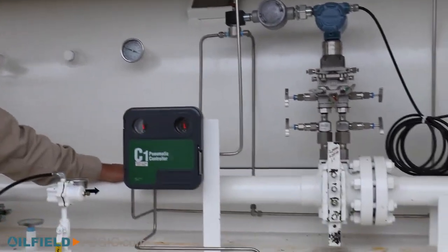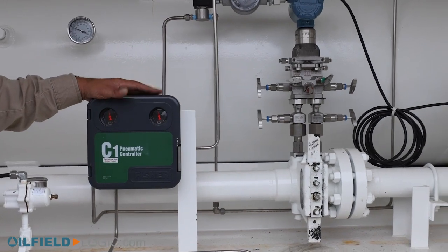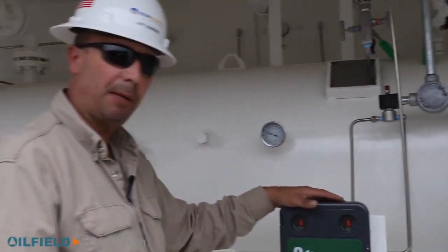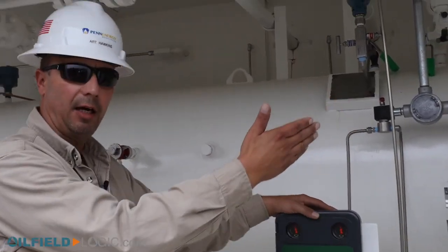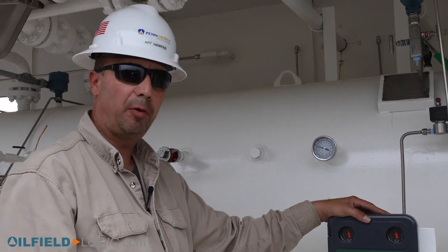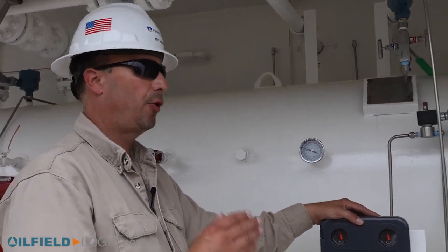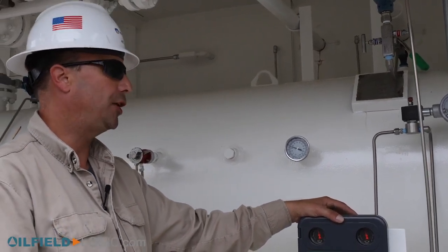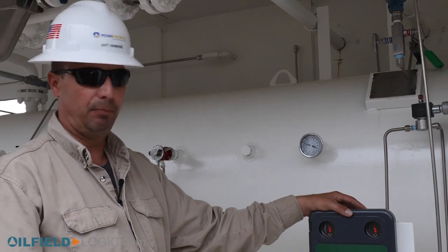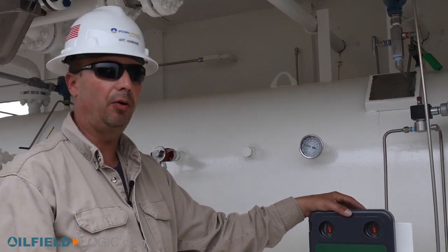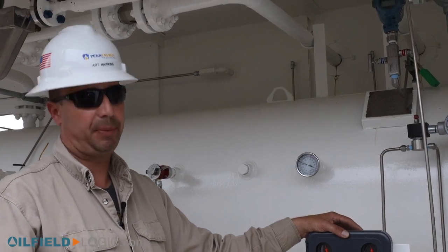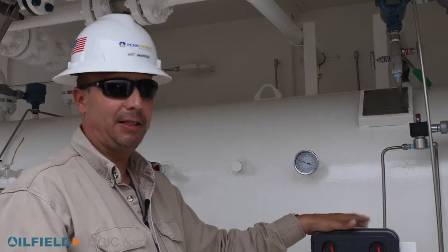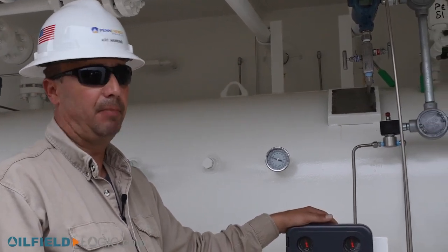Some of the safety devices that we have in this unit is this controller, which is our high pressure controller. When we get above a certain set point, that'll start to throttle back that inlet valve when we're getting out of where we feel comfortable producing our gas. It'll throttle back and actually get to the point of shutting that valve and stop flow, protect us from overpressurizing the vessel, and mainly due because of a compressor station going down or a curtailment or potentially a hydrate issue downstream. But this will protect us from overpressurizing the vessel and creating a mess.